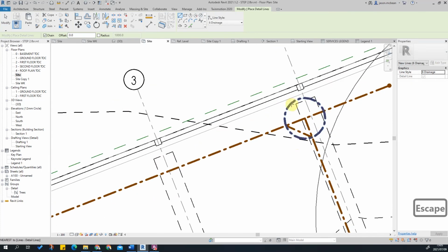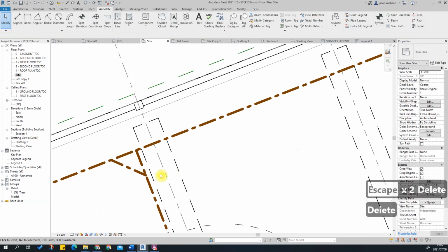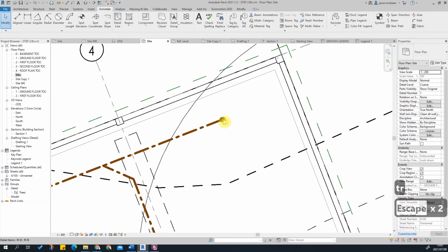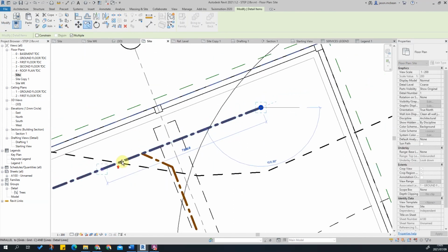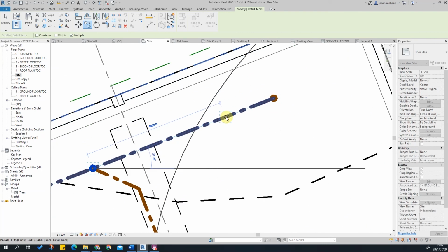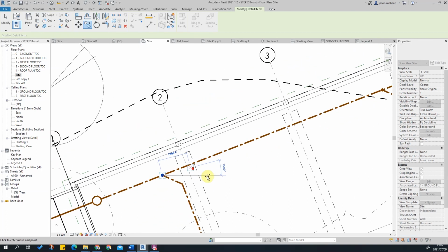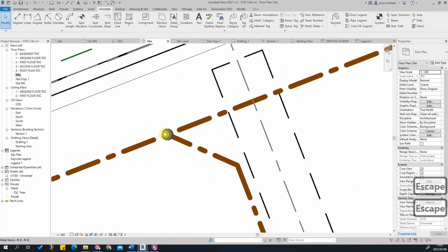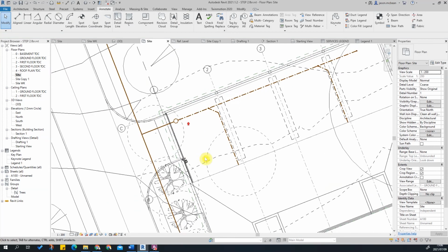Okay, get rid of the circle. And then all we have to do is trim, trim, and then copy the symbol. So where these intersects happen, that will be an inspection eye, inspection eye, and you might need another rodding eye somewhere in the middle here, worst case. Okay, but we've got inspection eyes, we've got a rodding eye, and you can see that the symbol will start reading. Okay, so there we've got our drainage.